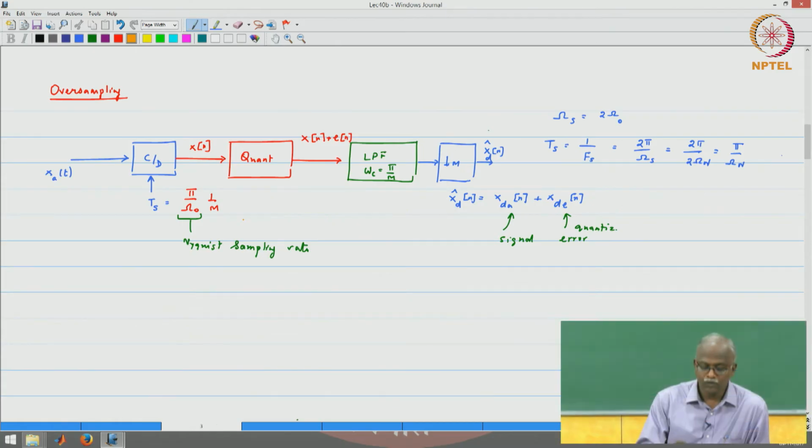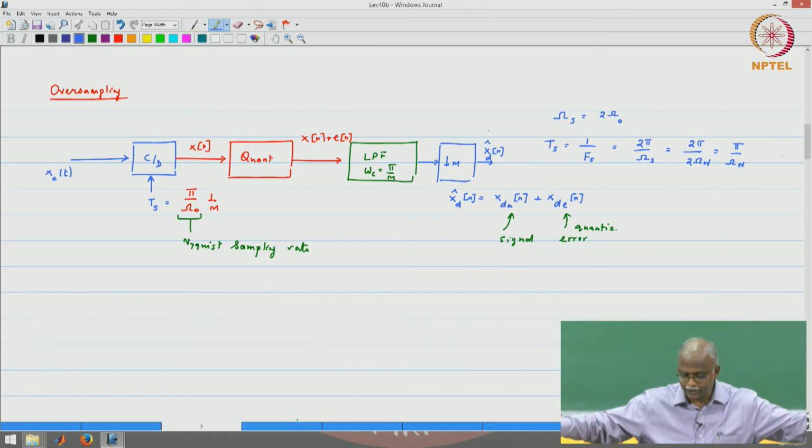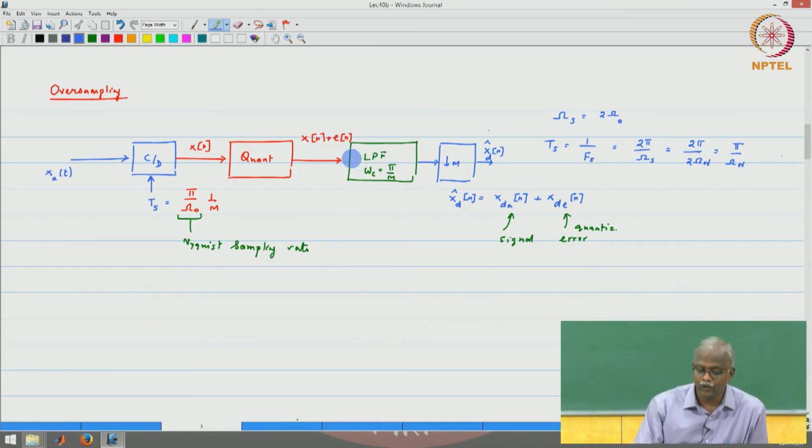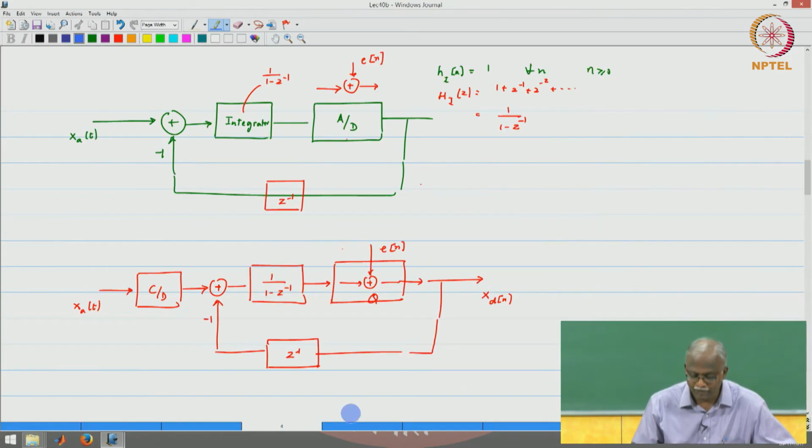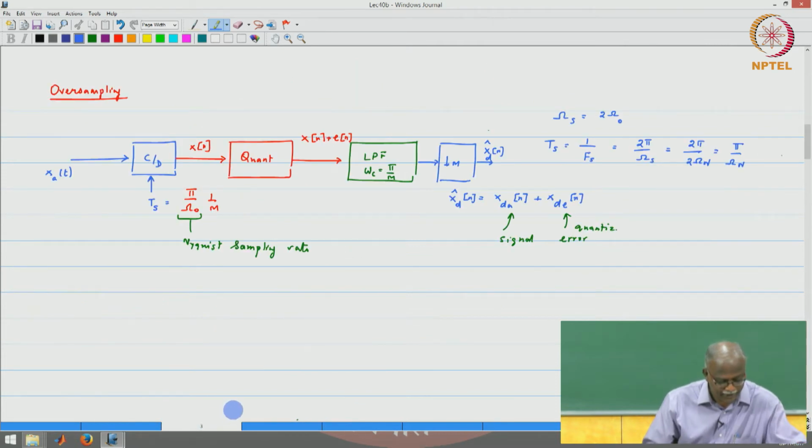Okay. Now, look at the oversampling element. Oversampling says I am going to do oversampling by a factor of m at the input. So, the quantization will happen like before. Basically, the quantization noise gets spread out, and then we use a low pass filter with the appropriate downsampling to get back to the Nyquist rate or as close to Nyquist rate. And we said that there is an advantage that we can get with the oversampling rate, and that oversampling rate based expression we derived yesterday.